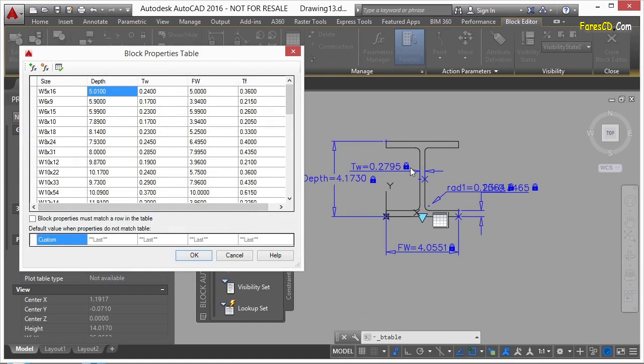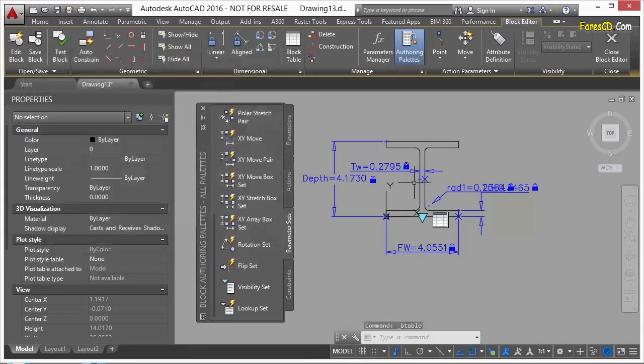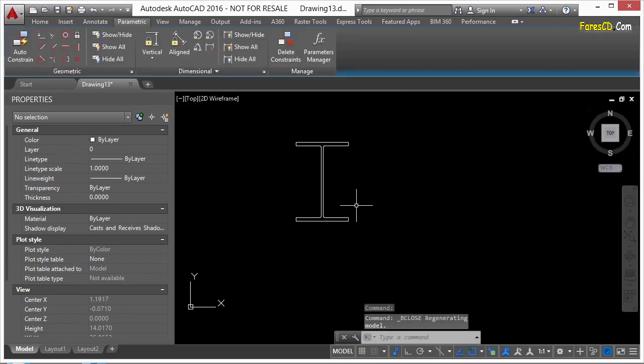And I can have one set of line work, just one basic shape, and then I can control all of its dimensions through my block. And I can only do that in this way because of parametric constraints. So that is a great application of geometric and dimensional constraints while fully constraining my object.